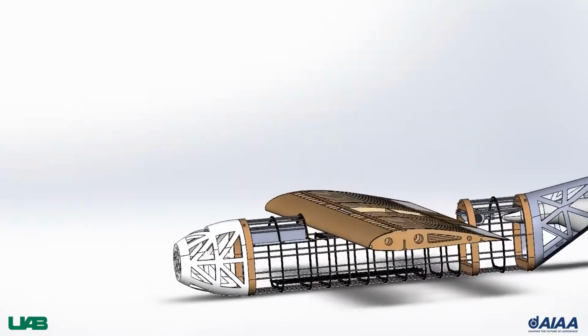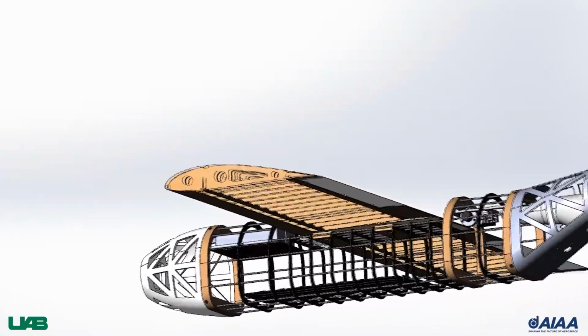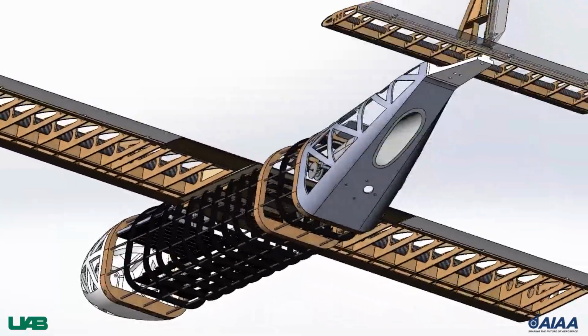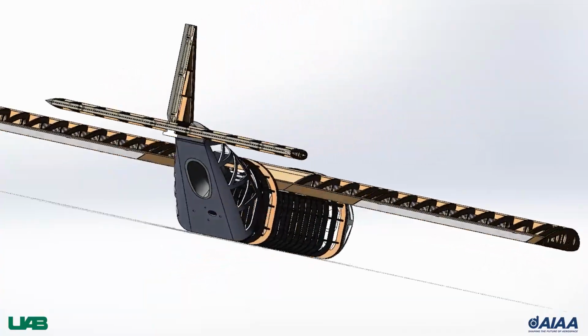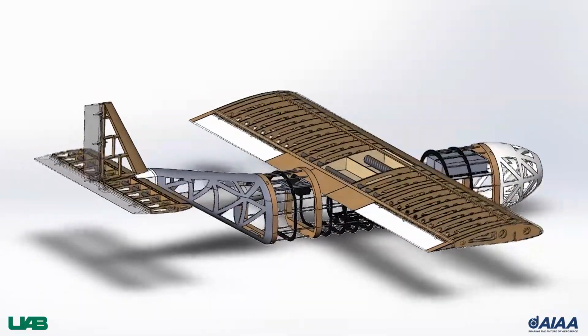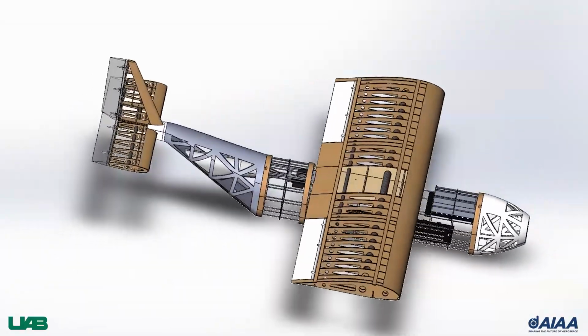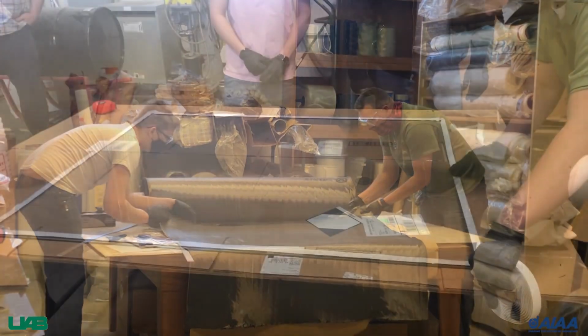The total length of the fuselage is 53 inches with the constant geometry portion manufactured with 0.1 inch thick balsa core carbon fiber composite ribs for the constant geometry section, 3/4 inch thick basswood ribs for the end connection, and carbon fiber rods to hold everything together. The carbon fiber composite was made and CNC'd here at UAB. The nose and the tail cone were 3D printed with PETG. The total weight of the fuselage is 4 pounds.